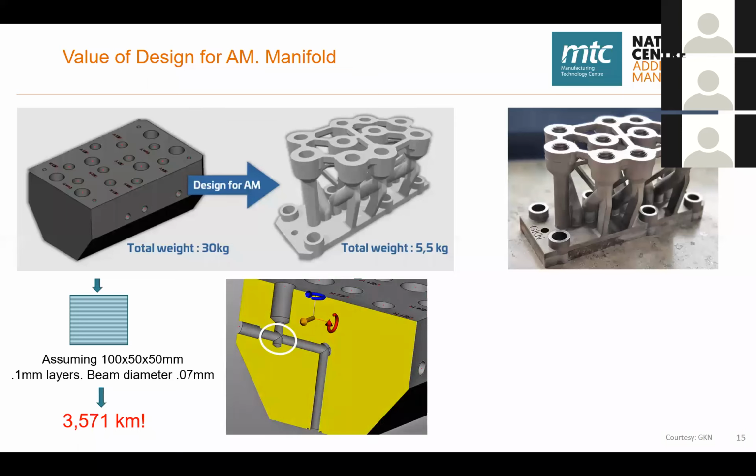In the case of the hydraulic manifolds, the way they are produced right now, what we have are efficiency losses, dirt reservoirs that cause failures, and as well we can have leakages between adjacent channels. So we have some issues already in the current manufacturing of manifolds.